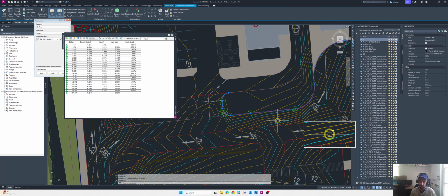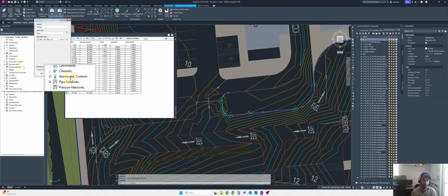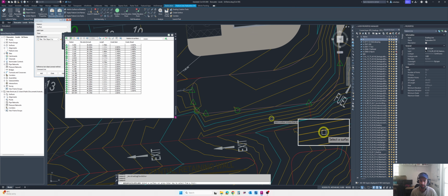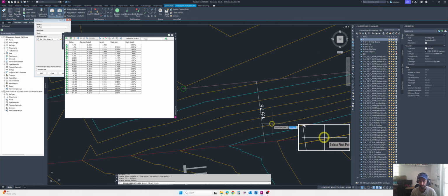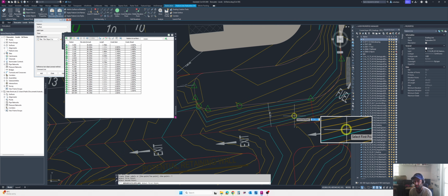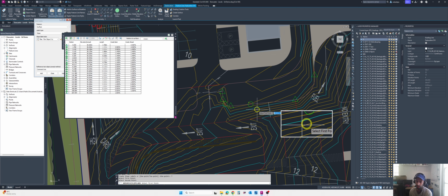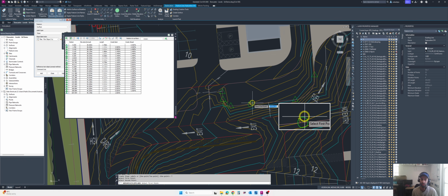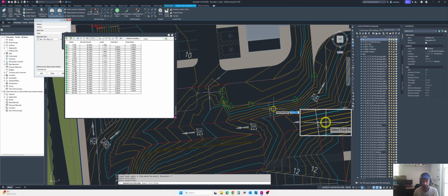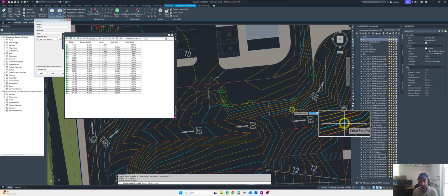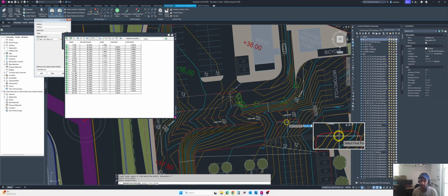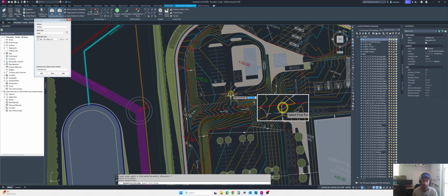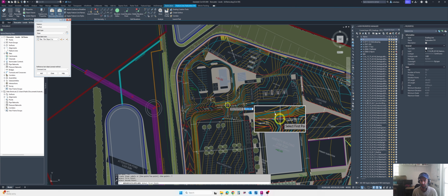the slope is very steep, I can see from the contours. So let's draw and see how much this one is. So 1 in 5, so it's wrong, and we again have to go and work it out. So these are the different tools that I will use to analyze, and spend time and time again to come to an elevation point that works for the whole site. But here I can show you different methods that you can use.